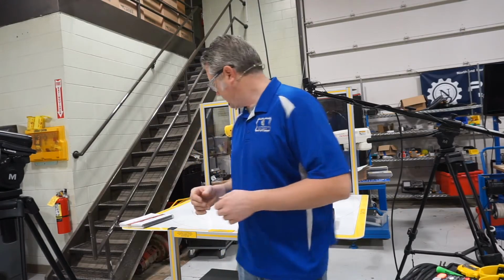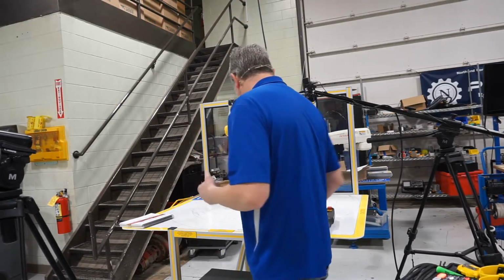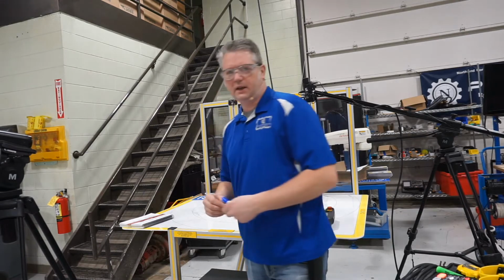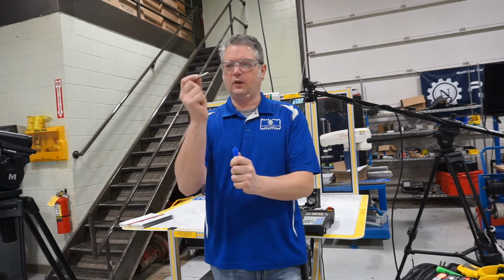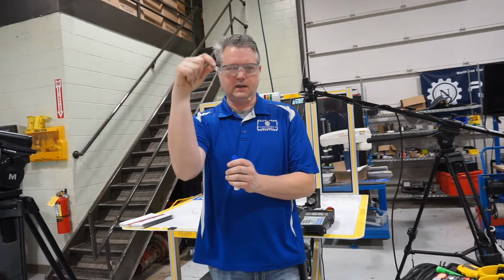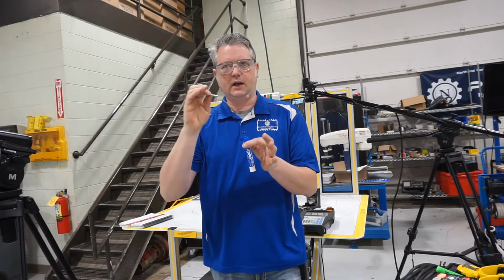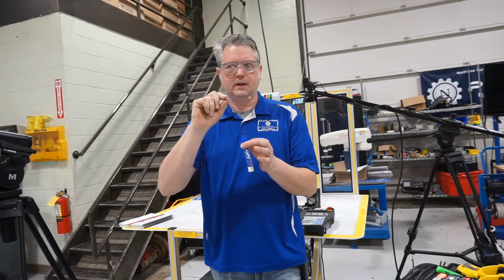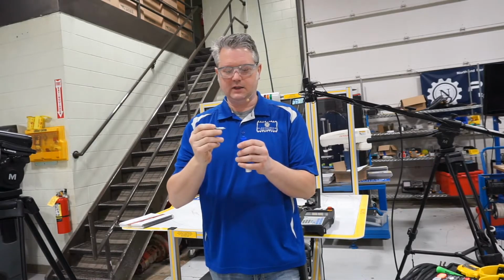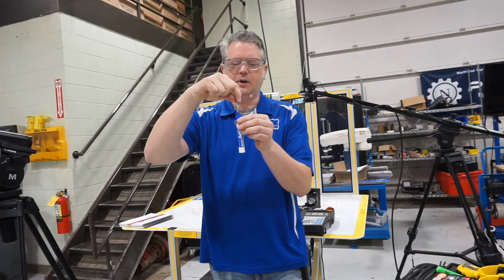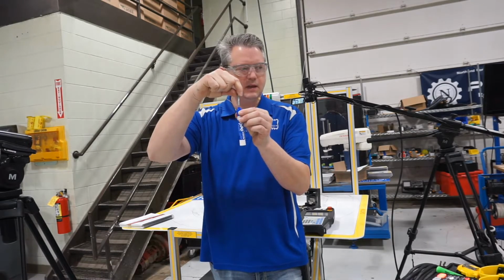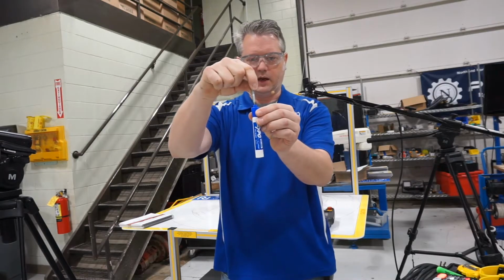The other way to do it is to do it in space, and that's a little bit more interesting, I guess. They have a few different methods. I'm going to teach you guys the 3-point method. If I want to figure out where the end of the arm is in space, three points will define it. So what I can do is this 3-point method. You come down and program one point by having the two tips basically aligned and touching one another.